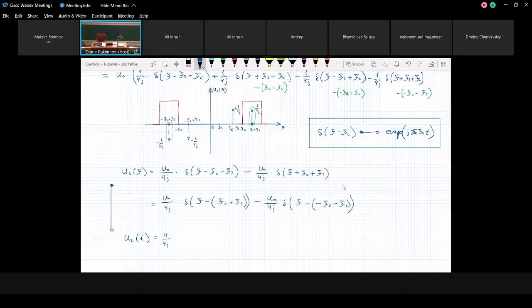So we place this imaginary amplitude in front of it, and then we place our exponential function. Or I can write it the way we did before, j pi, and then the frequency Fc plus Fs times t.